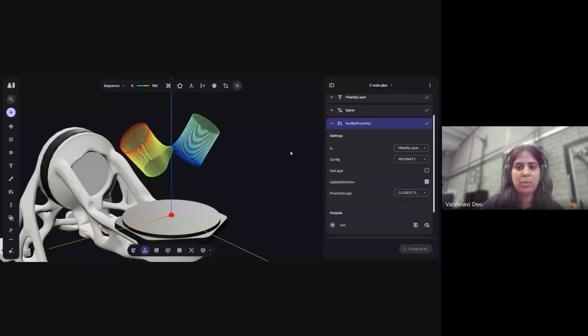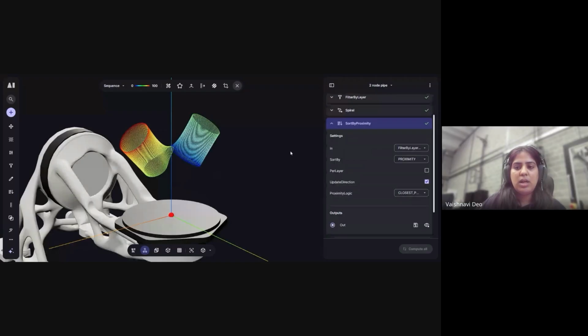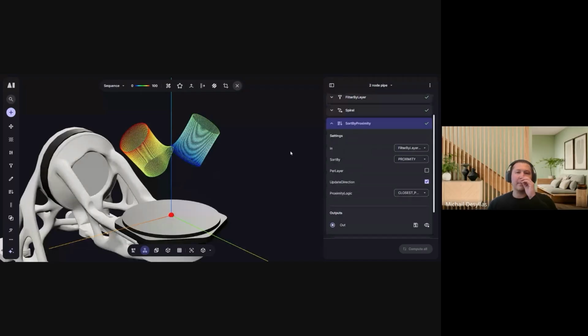So what I am doing next is I'm filtering it by layers. I am going to filter the first segment out, because from here to here it's like one section, and what we see next is two branches coming out, as you see here. The reason I'm doing this is I want to separate the segments out so I can spiral them individually and reduce jumps. Makes sense.